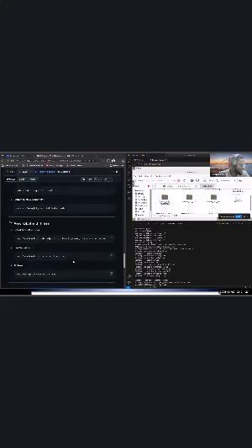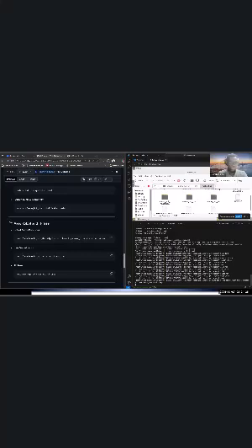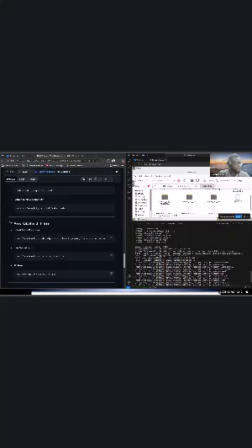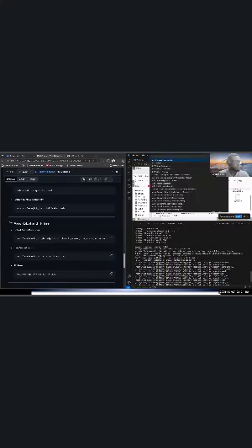Let's run the robot state publisher. Just copy this and paste it. The robot state publisher publishes the different links and joints, the state of the robot. You can see we have the base link, the camera optical frame, all that, on the robot topic. Now in VS Code, you need three terminals.